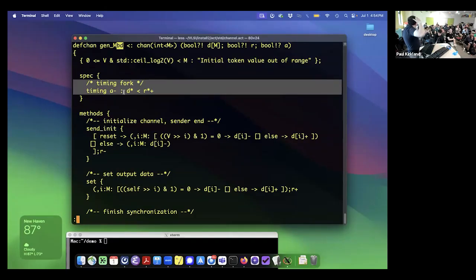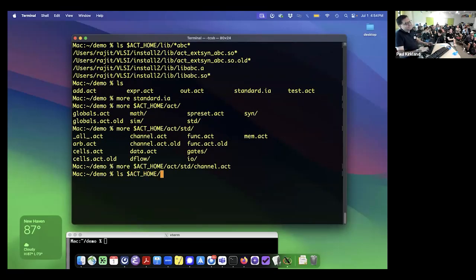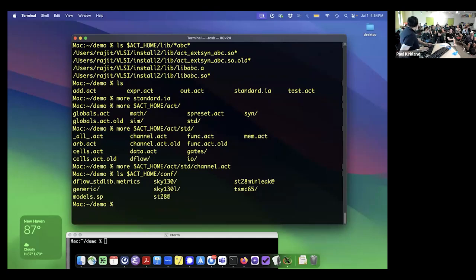If I have a new PDK, how do I get my gate delay information? Everything is in a configuration file, which I didn't tell you about, for different technologies, which has all of this information. But we can talk about it when we install. I think it would be nice to show it completely. I have a cell characterizer as well, which generates .libs for you, things like that.